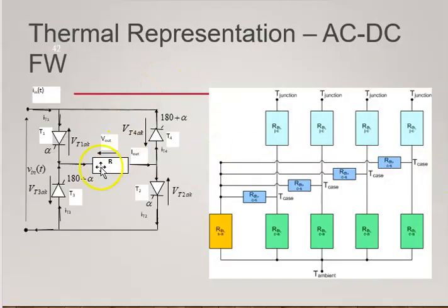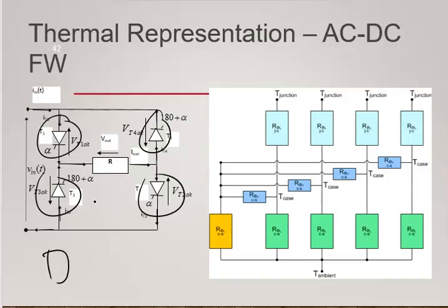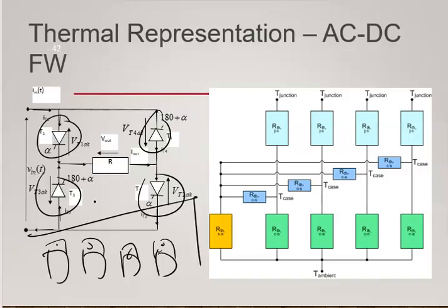But when you have, for example, a full bridge rectifier, it comes in a module or it comes as individual thyristors. This is a thyristor. We have the triggering port here. So these might be attached to one heatsink. You have 4 devices here, and you have 4 devices here, which might be attached to one heatsink only, or you might have an individual heatsink for each of them. It depends on the design and on the constraints of your module.